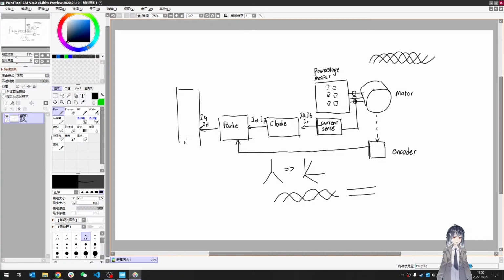Okay, so here we have a PID controller that takes in the current and takes in the IQ, ID target current, and outputs VQ and VD, the desired voltage on these two directions. And then we do inverse Park to get V alpha and V beta, basically converting the DC values back to the rotating frame. And we also need encoder inputs here.